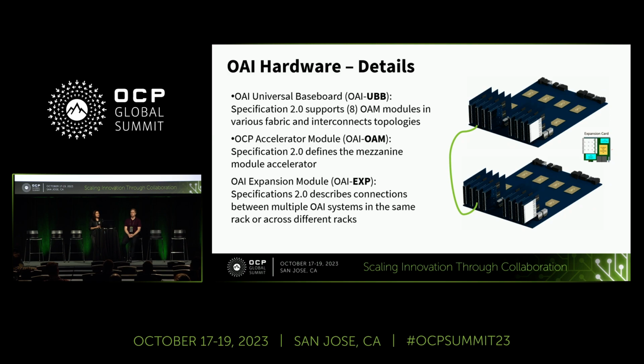So Song and Ahmed gave an update on where the specs are. And again, we want to stress what is critical in terms of this signal integrity study. The OAM universal baseboard has 8 OAM modules, which is significant, because when you have 8 of these modules located, the longest trace length becomes very important for signal integrity.